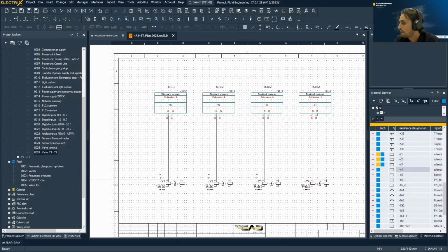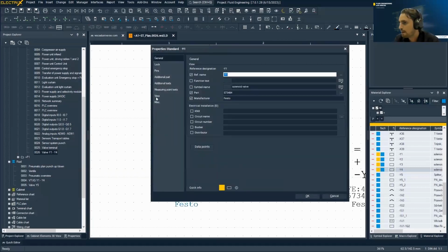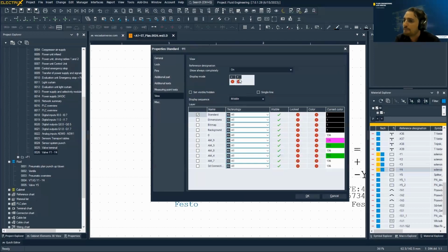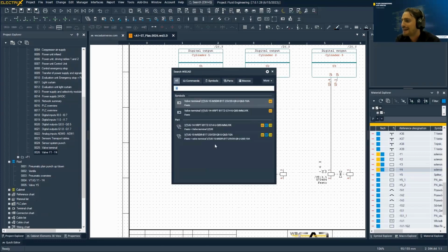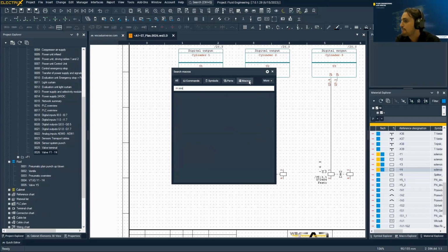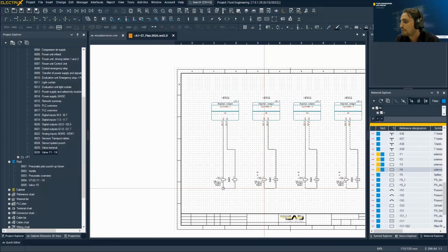And again, you can see this cross reference is created automatically. And you can see this reference here. We don't have any structure. If we would have a structure, all paths would be defined. We would know exactly where this belongs. Now you can see macros. We will insert some macro, also from this quick search, which is some new functionality in WSCAD electrics. We can use it a lot for all cases, macros, parts, symbols, and when we start to use it, it's very beneficial.